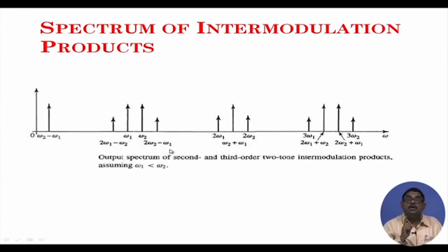So, third order intermodulation, where from it came? Because of nonlinearity it came. If the system was linear, these were not generated. Now, nonlinearity also generated harmonics, but by filtering I can always remove them, but these I cannot remove. So, they will disturb me, that is where I will have to be more clear.